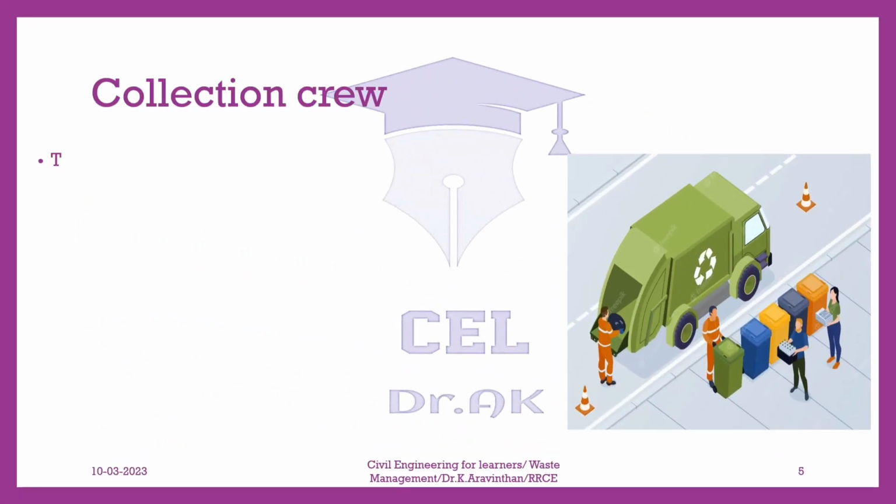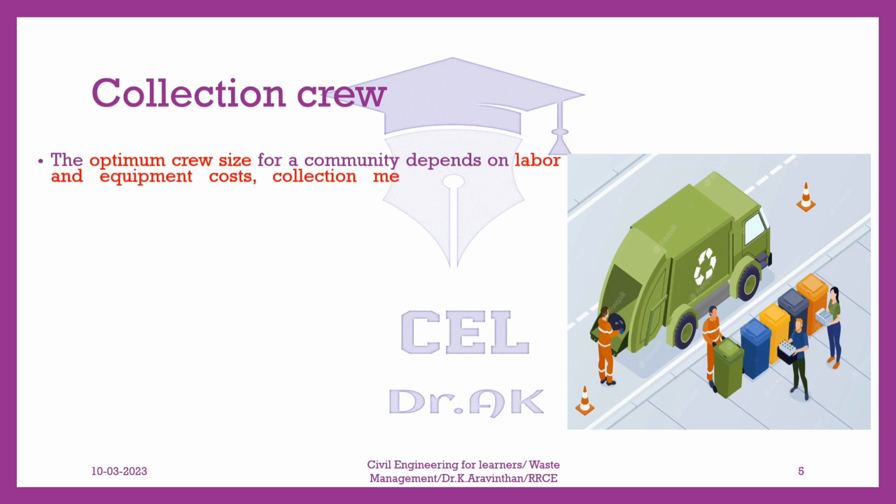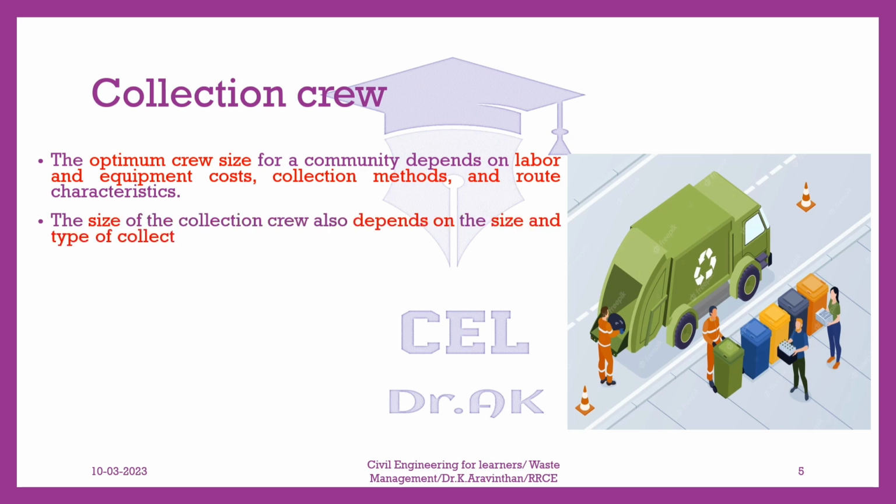Collection crew. The optimum crew size for a community depends on labor and equipment costs, collection methods, and route characteristics. The size of the collection crew also depends on the size and type of collection vehicle used, space between the houses, waste generation rate, and collection frequency.